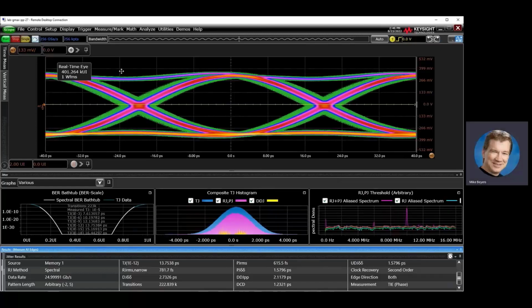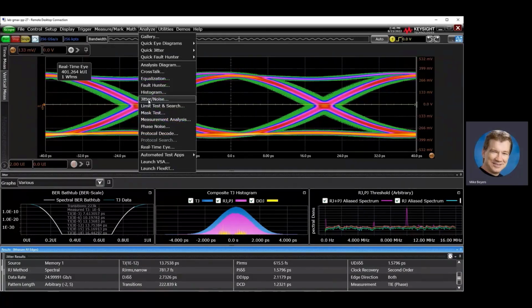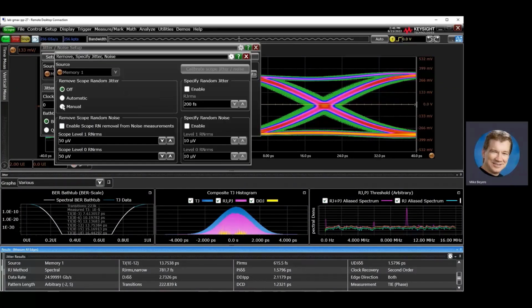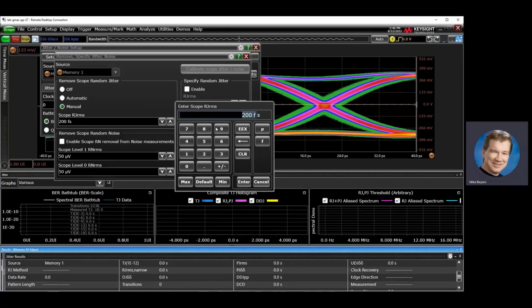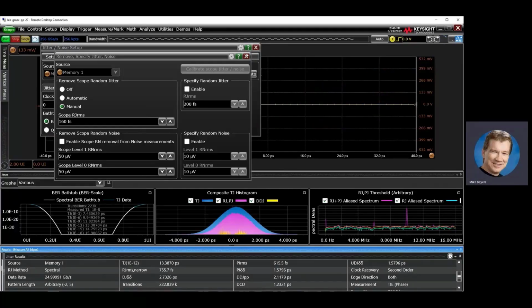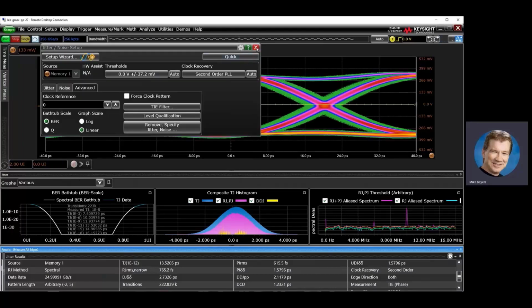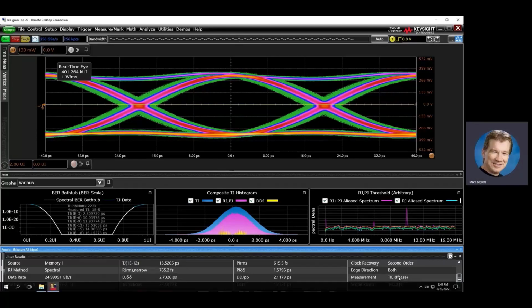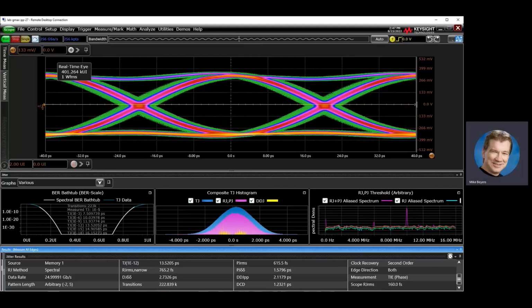So increasingly, we look to compensate the noise of the oscilloscope. It's always best to start with the lowest noise, widest bandwidth scope you can get. But also then, when it comes to the J-edge jitter measurement, the SNDR measurements, we can try to compensate for the oscilloscope contribution to that noise, to back out a bit of that contribution and get the customer some more test margin. It's really an emerging measurement science area, and it's an area where you're going to want to definitely get the most recent revision of the software for your Infiniium oscilloscope, because we're constantly making improvements on that.